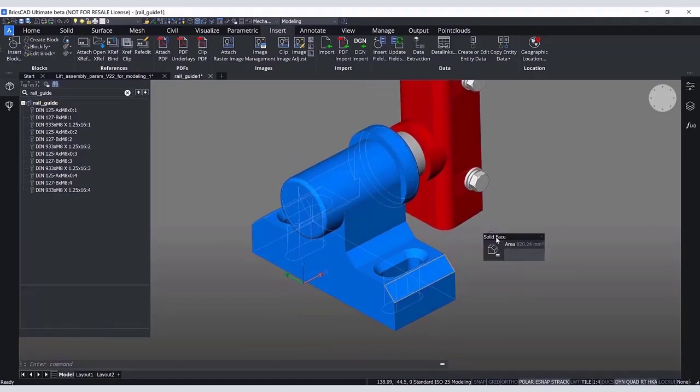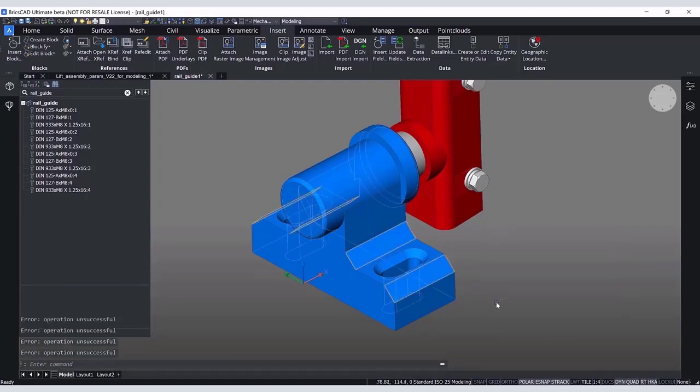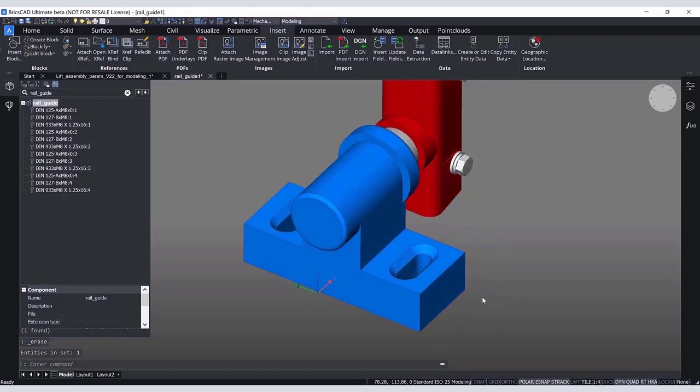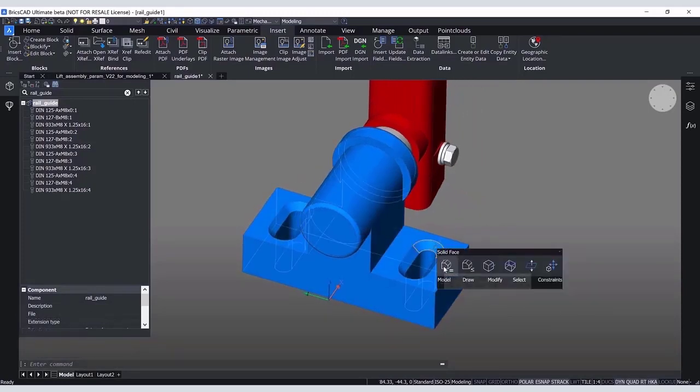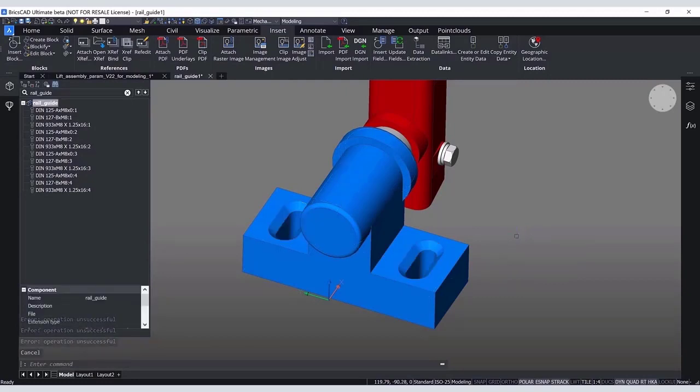How can we do this? Of course, we can always just manually select required faces, but now we have a faster way. As you saw, we use a new tool which allows us to select chamfers with the same offsets. It is part of the very powerful dmSelect command, and if you want to feel the full power of this command, you need to call it directly. It allows selecting faces and edges by attributes like area, length, and a lot of other possibilities.